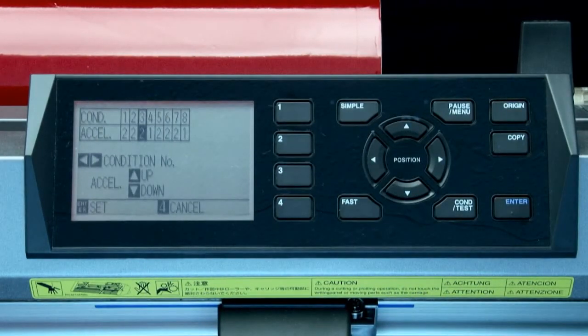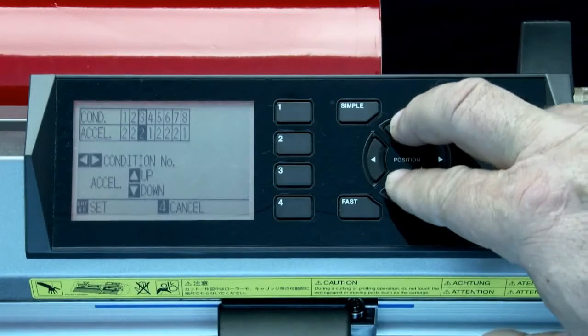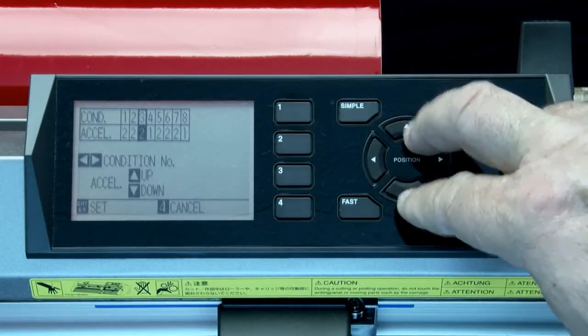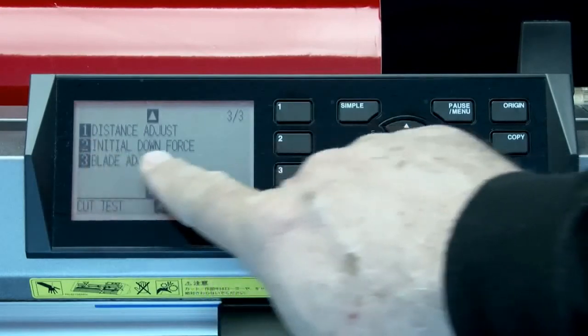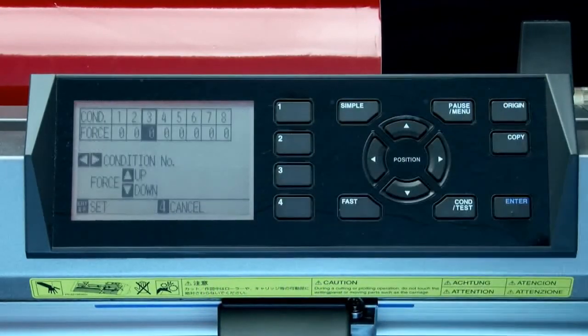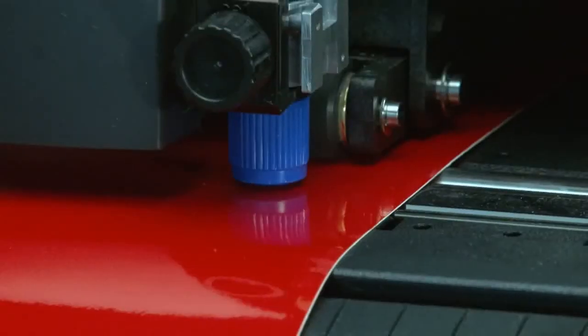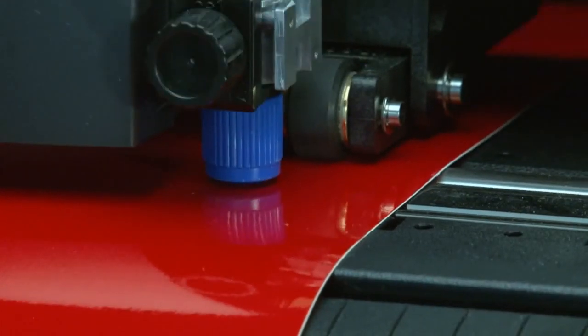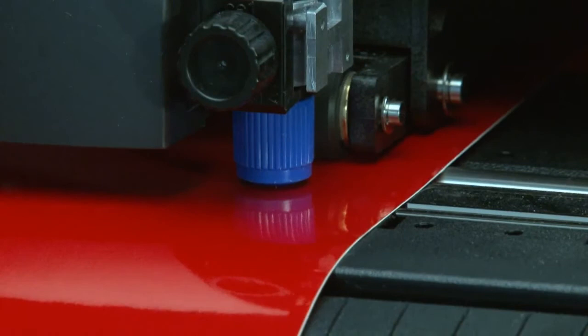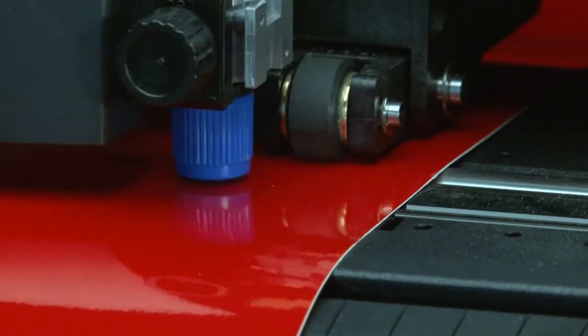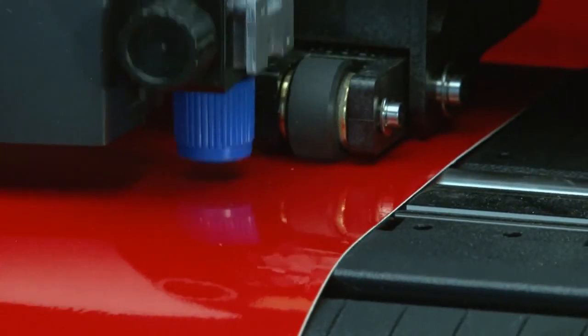If you have an intricate design, or if you are cutting thick medias, you may want to decrease the acceleration. This way it will avoid pulling up the corners. Normally, default is best. Tangential emulation is a setting used for cutting thicker material. As the cutter comes to a corner, it will slightly lift the blade out of the material, place the blade on the material, position the blade in the next direction, and then continue cutting in that direction.